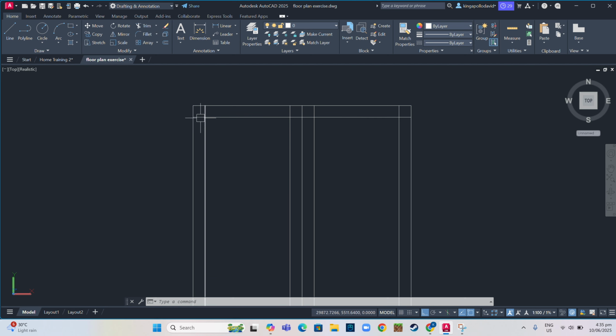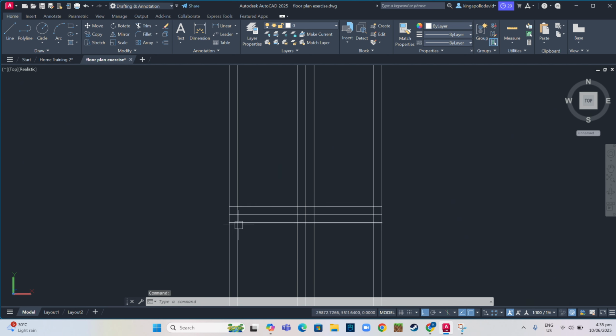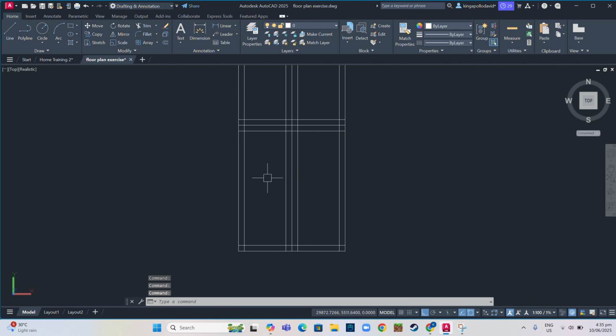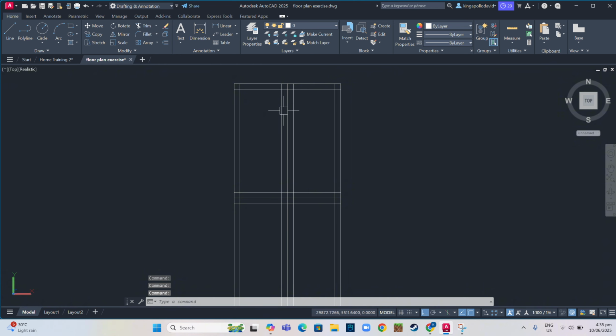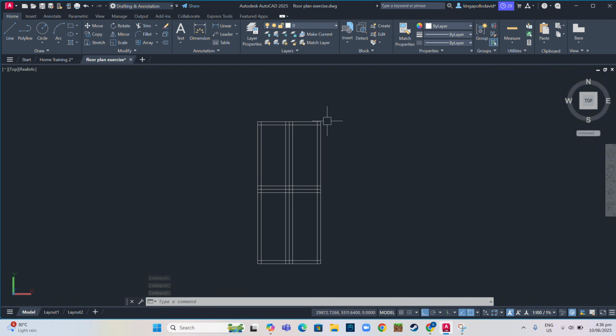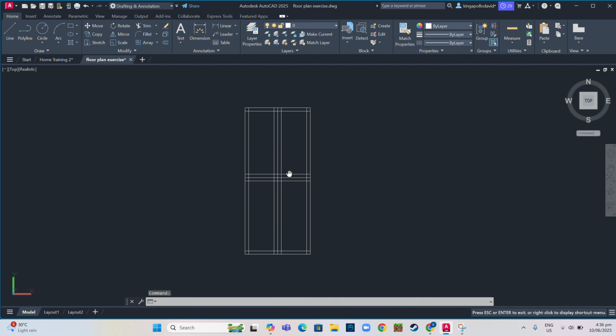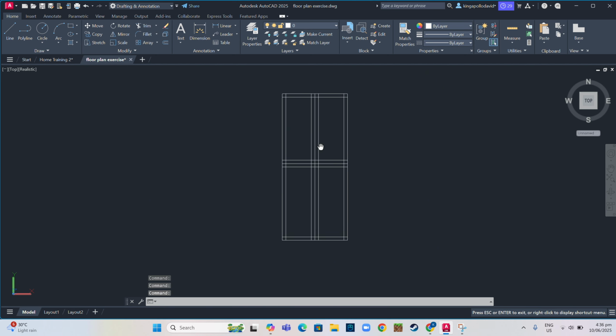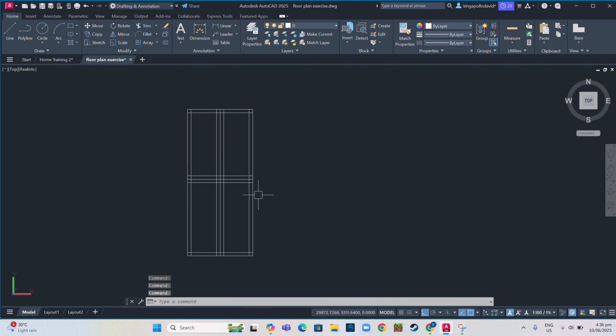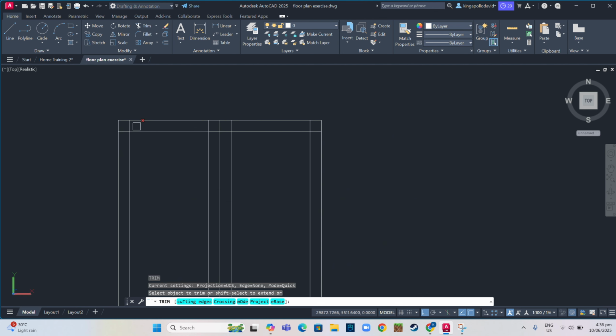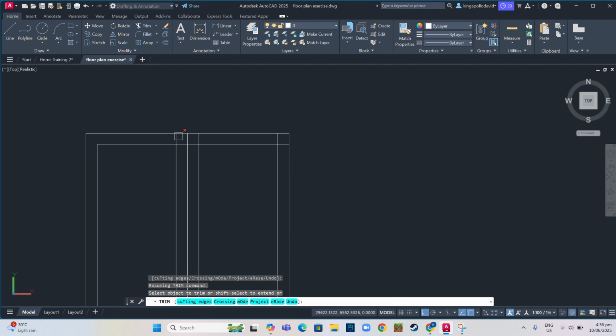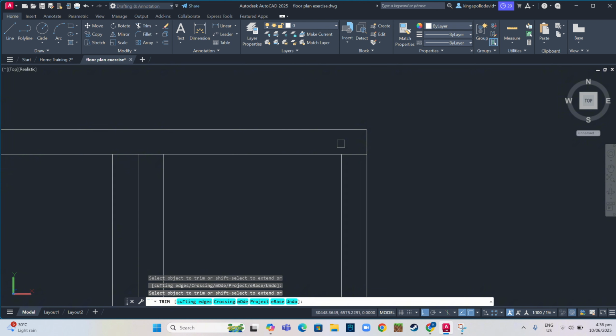Now all we gotta do is trim these things right here, on the side. Now after trimming those, we can then proceed to creating 3D lines or making this door a 3D object. So this is just a 2D line. We're just creating the design of the door, the front door, in an aerial view. So trim, just trim all of the unnecessary things, all of these right here.